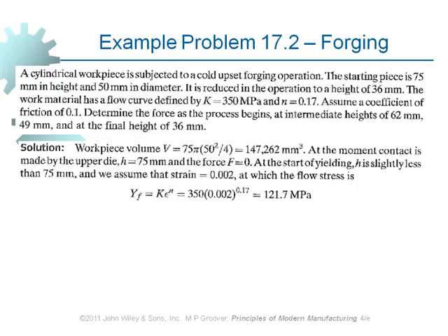So this is what can be computed then. If we substitute 0 here, when there is no strain, no deformation is possible, so we get 0 for the whole equation. But because we are deforming the material, strain cannot be 0. The material has to get elongated before it is deformed. So it is something more than 0, and by default, we consider 0.2% of the total strain.